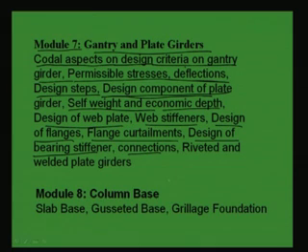And as we know, plate girders are of two types, riveted plate girder and welded plate girder. Two types of plate girder we use in practice. In both cases the design has to some extent similarity, but there are also many differences in terms of connections, and in terms of finding the minimum depth, that is the economic depth.